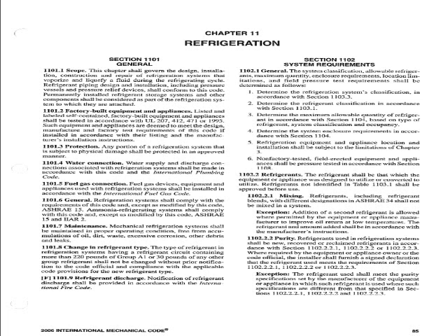It gives some definitions, for example, factory built equipment and appliances, protection, water connections, fuel gas connections, which again will refer to the International Fuel Gas Code, because the International Mechanical Code does not cover fuel gases. It talks about the maintenance of the equipment and talks about refrigerant discharge. And again, for refrigerant discharge, it talks about the International Fire Code.